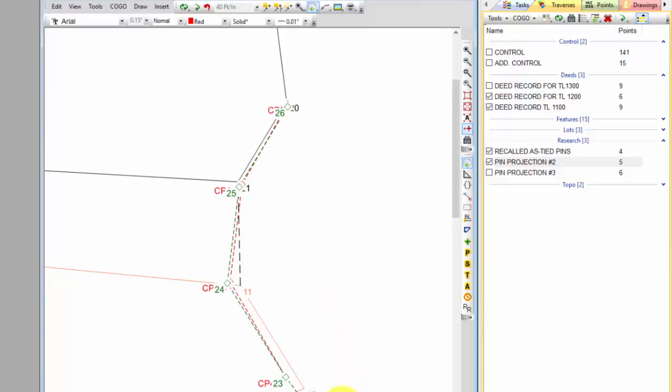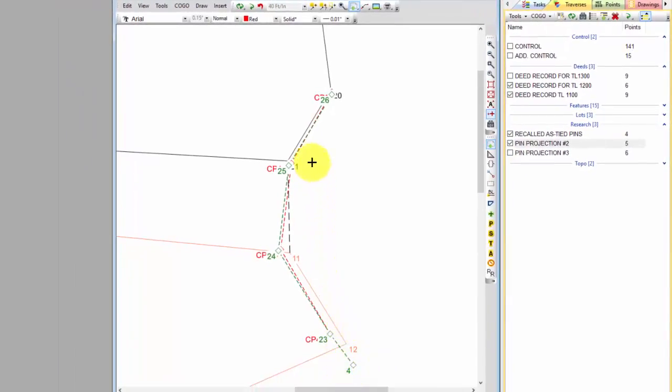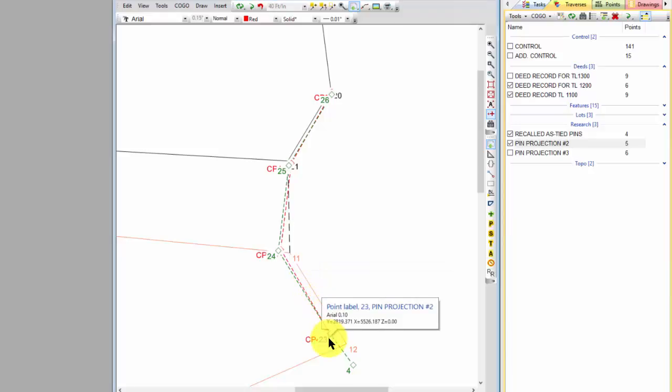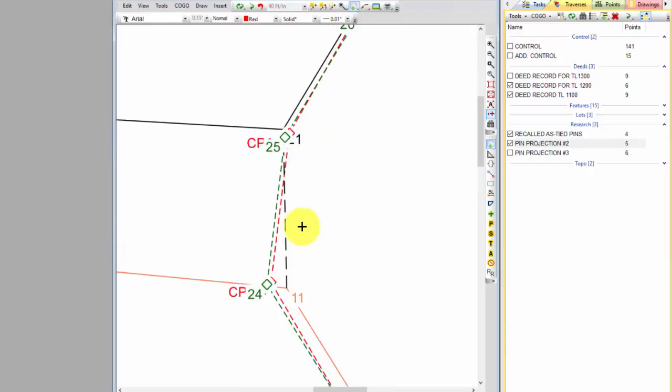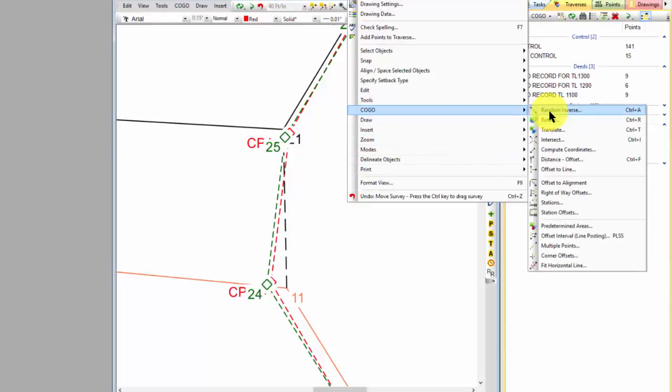And I'm pretty sure that I can come up with this corner of this tax lot that I'm interested in if I hold some of these deeds, or if I go back to these original surveys and do the measured bearings and distances through this control point here and this control point here. I'm going to be off a little bit on a couple in between. And I can do the random inverses and take a look at how much that might be off. Let's just do one of those quick. Let's do a random inverse.